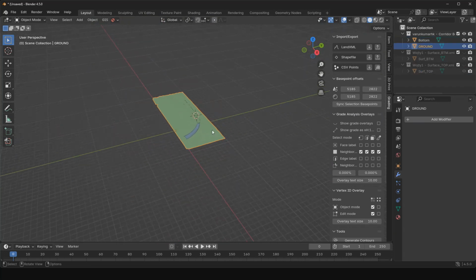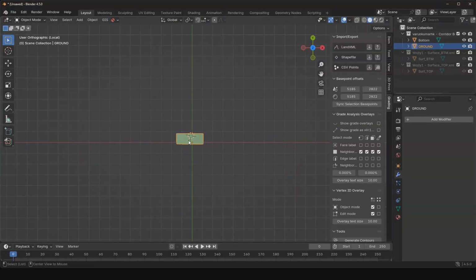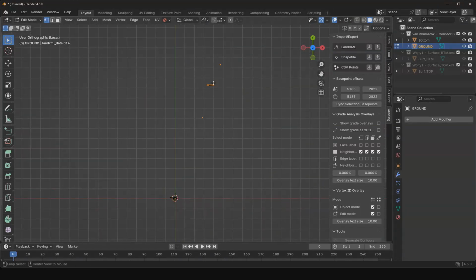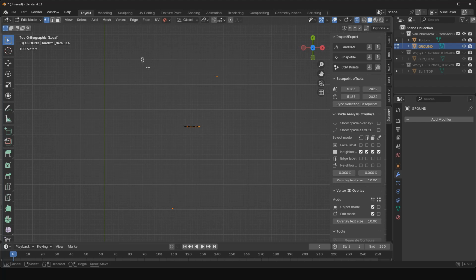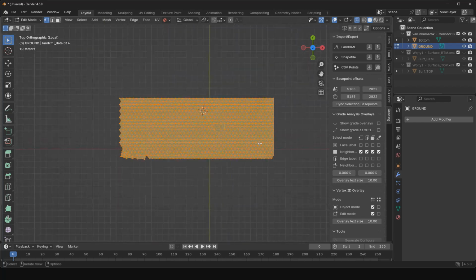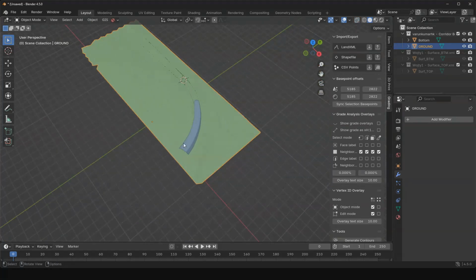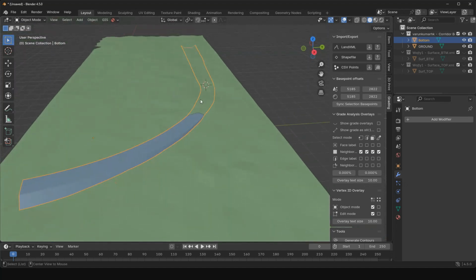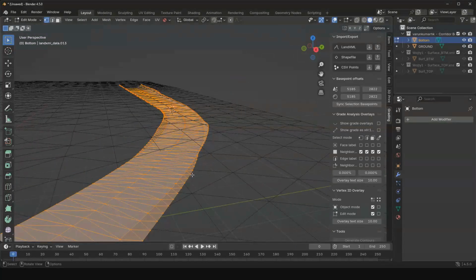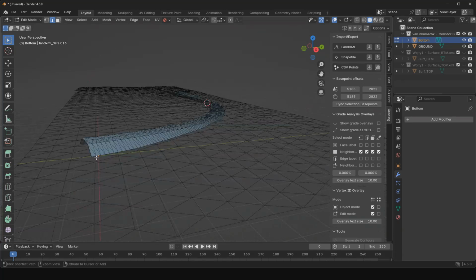The first thing I will do is, when you export LandXML of this surface from Civil 3D, unfortunately it includes some random points. Maybe the original author would know why these points are here, but I'm just going to delete them as I don't need them, and neither are those 2 points. So I arrive at my clean surface and the road here. I do see also that the road was nicely clipped right on the surface along the edges here.